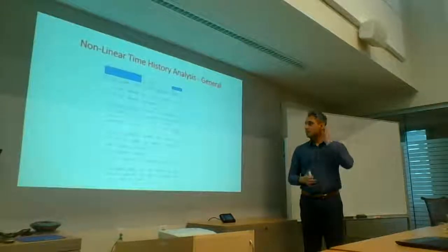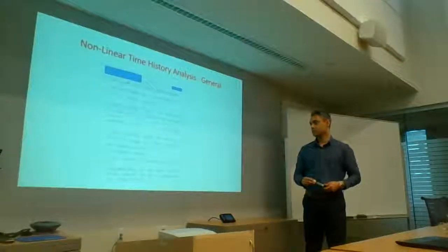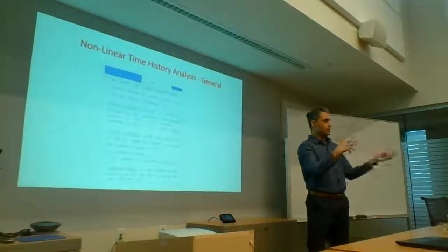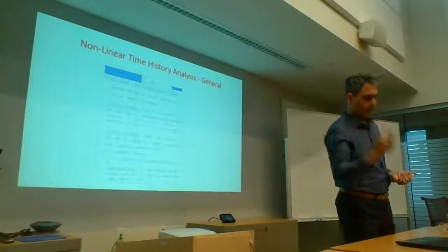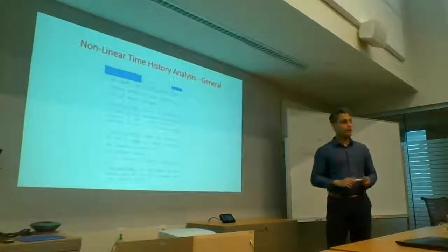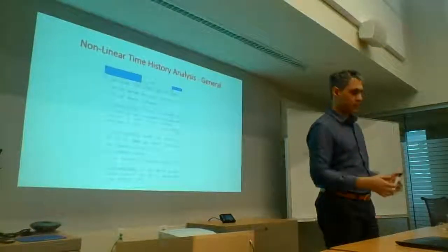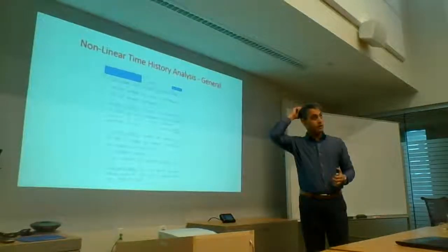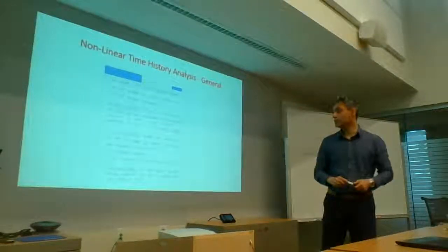With the implicit methods, you cannot directly determine the next time step value. If you go into some of those, you can see that i+1 shows up on both sides of the equation. Nevertheless, there are ways to solve it. I'm not going to go into it, but go to Chopra's book, look at chapter 5, and there are very nice formulations that you can pick up very quickly. You can even program those in Excel, or I guess you guys are way more bright than I am in terms of programming. I tried to do a little bit in Excel many years ago. So MATLAB or anything else, you can do those.